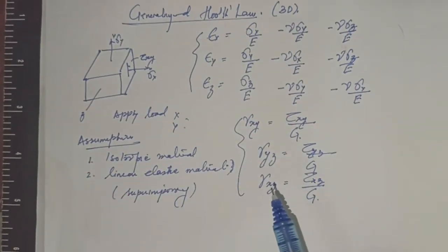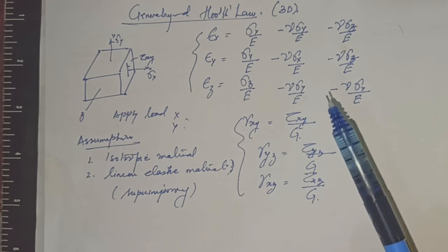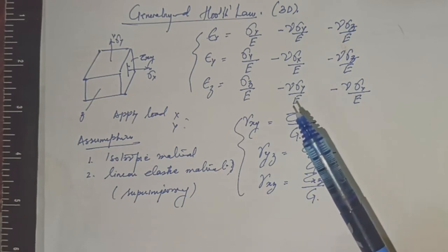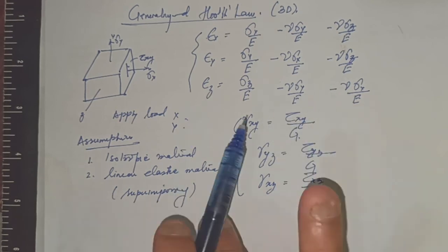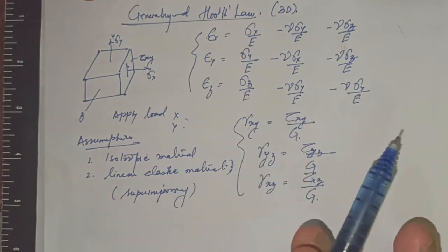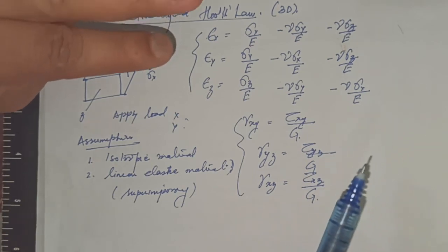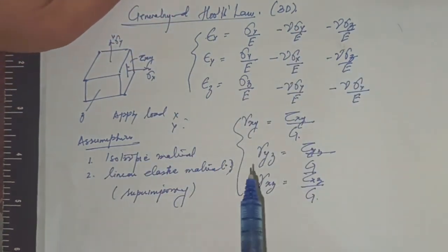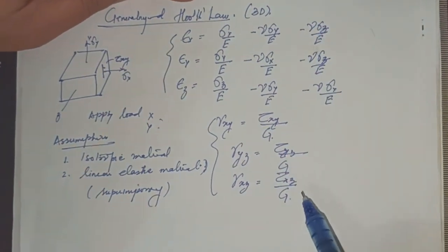And with the help of this, you will be able to obtain different values of stress and strain components of the stress tensor. So what happens in this actually? Stresses and strains are combined. The stress tensor and strain tensor earlier were separate. However, in this, the stress and strain tensors are kind of combined. So this is the generalized Hooke's law.